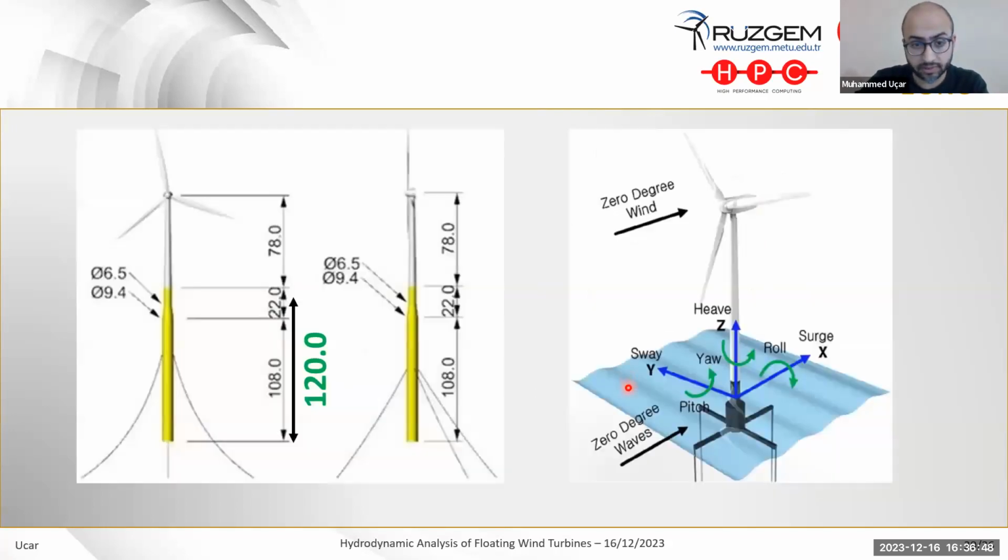While using hydrodynamic analysis with HAMS, we are not defining the moorings. The moorings are defined on the OpenFAST side. That's why we are using the 0-degree waves only for the spar buoy. And regarding drawing these structures, we will just draw the submerged part. Otherwise, HAMS cuts out the unsubmerged parts with its own tools. But it's better to draw it in a certain way.